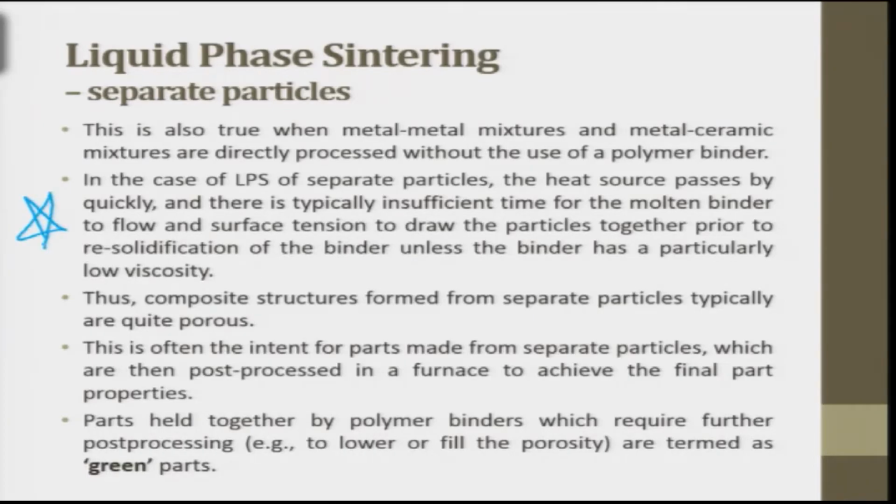Very important point: the heat source passes by quickly, and there is typically insufficient time for the molten binder to flow because it is very small in quantity. Thus, composite structures formed from separate particles are typically quite porous.